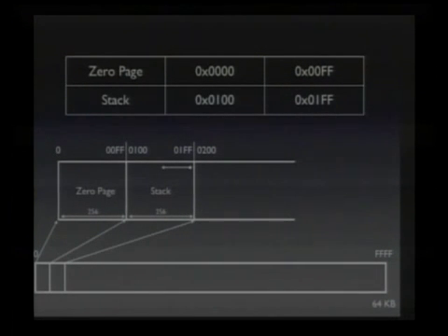Page 0 in RAM is special. I'll talk about this one later. Page 1 is the stack, so the stack is always confined to those 256 bytes. The stack starts at 01FF and grows down.